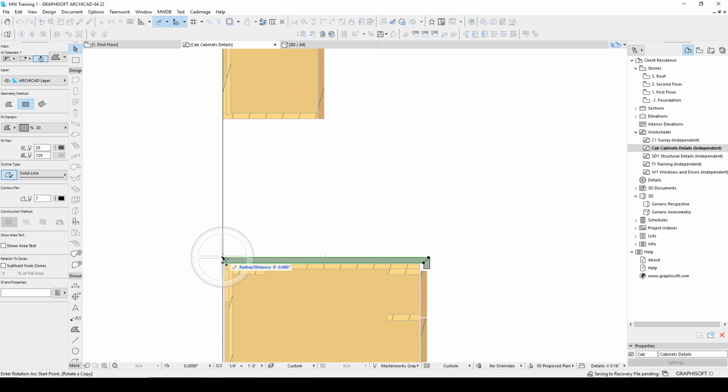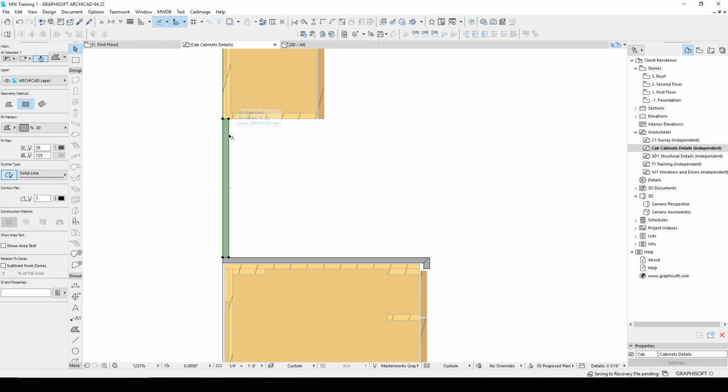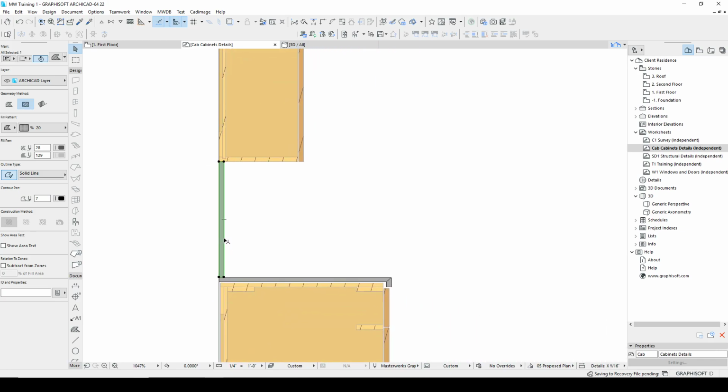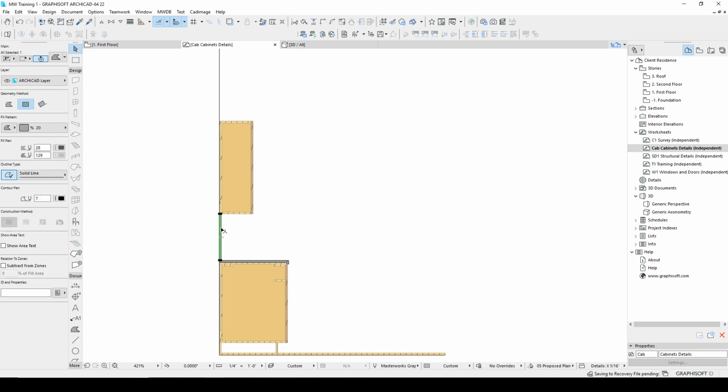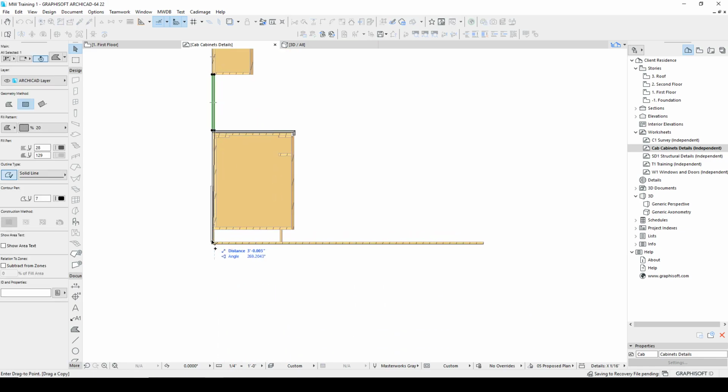I'll use F10, which is a copy rotate, move this up, hit S to trim this, hit delete, and there's a backsplash. That's a slab backsplash. Maybe it's tiles, so I might adjust it. If I wanted to show the drywall on the wall, no problem.